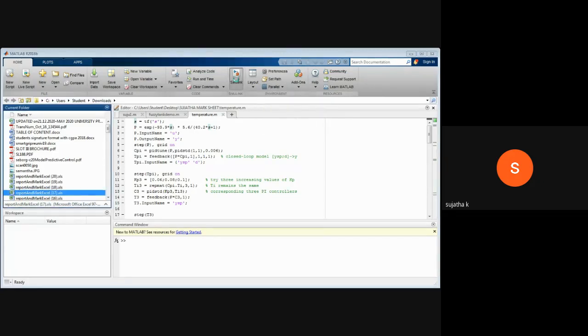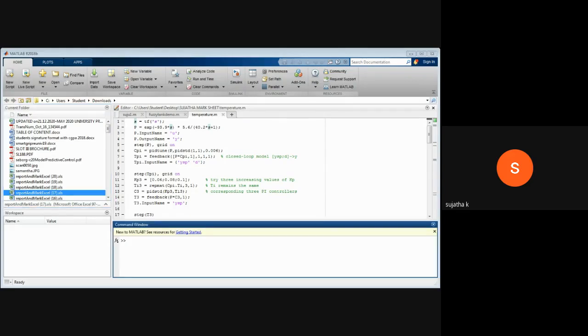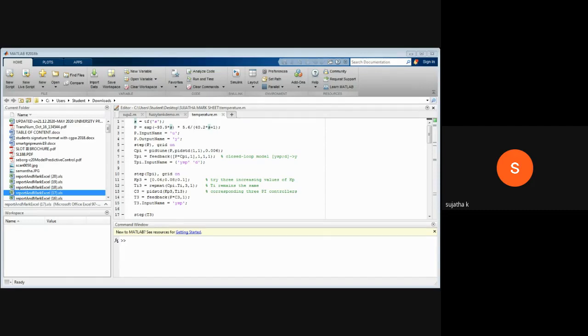An untitled Simulink file will be opened. Then you have to click this. So when you click that, the window will open like this. This is the library actually. So click on the library, and you will have the components opened.